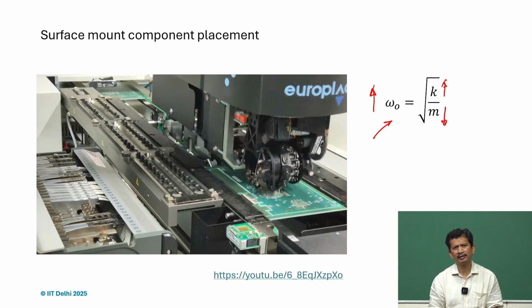We will also learn why loading in the axial direction is preferred over bending and torsion when it comes to achieving high stiffnesses. At the same time, when we are looking for compliance, less stiffness, where we want to get adjustment easily in certain directions, why we go for bending and torsional loads or deformations. So, we will stop here today and we will continue from here. Thank you.